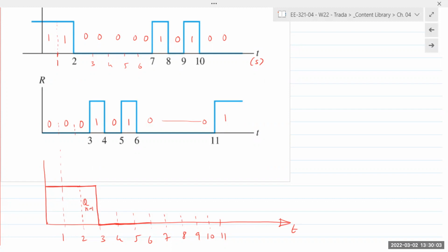Let's see, where was I? So going all the way up to 7, the output doesn't change, right? It stays at 0, 0, 0, 0. Reset is 1 here. Here it's previous state. Here also remains at previous state. Both of these time periods 5 and 7, where input R and S are both zeros, output is the previous state, but the previous state for both R was equal to 1,